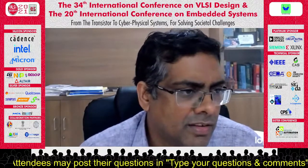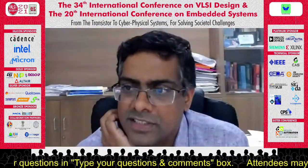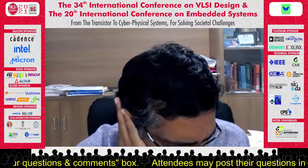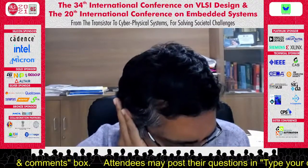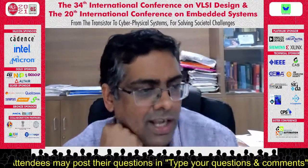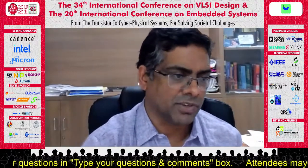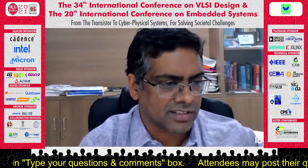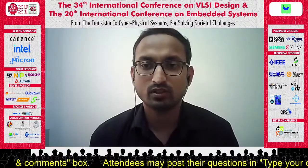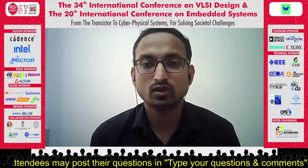No question. All right. So Sasank, it's a very interesting presentation, and I have a few questions. One point: you told that with self-heating your current is reducing, right? And current and gm everything will reduce. So is this mostly because of electron-phonon interaction, or are there any other reasons you are talking about? Yeah, mainly because of carrier-phonon scattering, because we have considered both thermodynamic and hydrodynamic models in our simulation. So it is mainly because of the scattering phenomena.